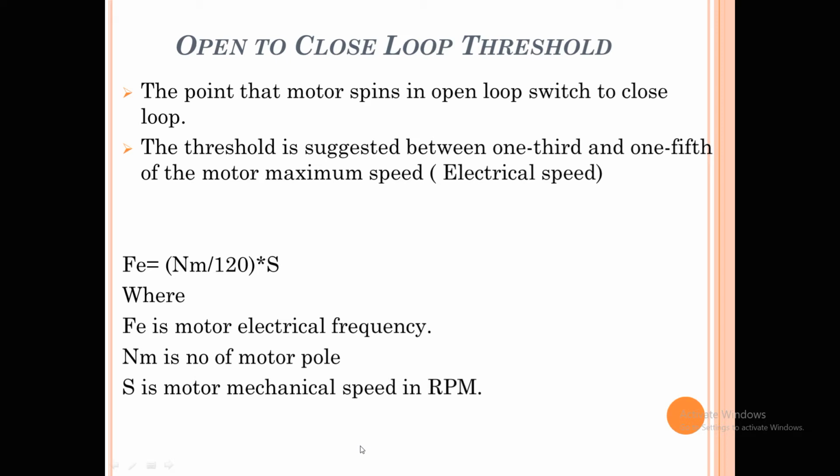If you switch at a sufficient RPM, say mechanical RPM of around 100, it is okay. If you switch at a very low value, the back EMF sensing may not be good, so the motor will not be able to switch. In that time very high current will flow and the motor will go into overload protection.